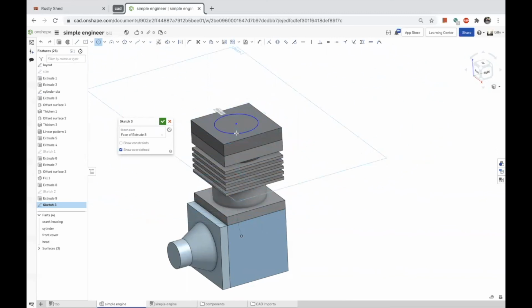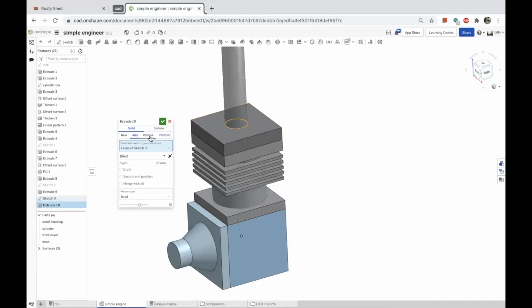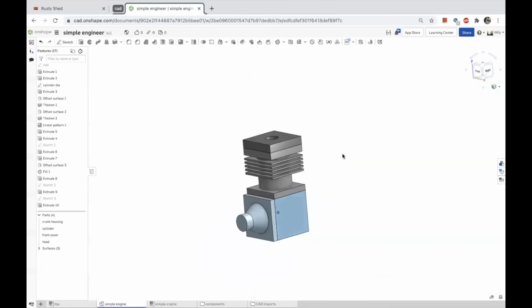And I am picking up the reference down. Let's go ahead. We'll dimension this. And we'll put in 1/4 of an inch and we'll blast this through. So let's go. This will say remove. And this hole will always go through all, and then it automatically figured out the right scope. And now we got that.